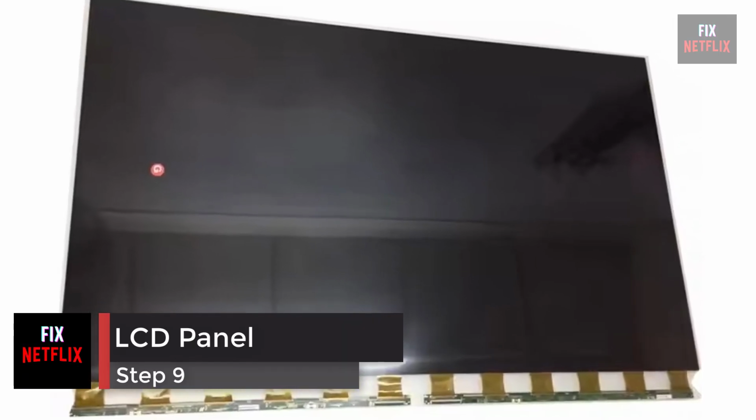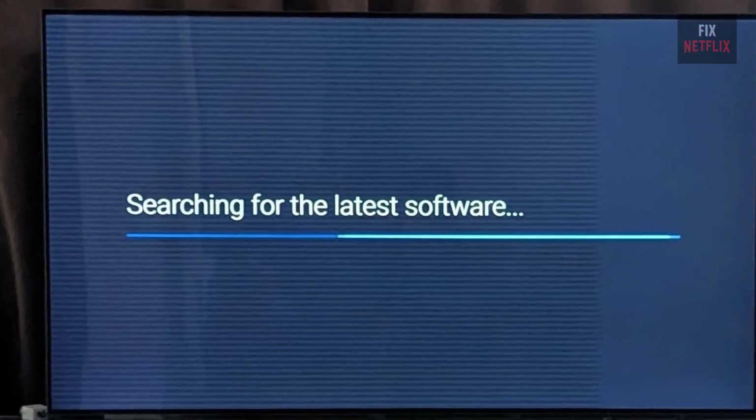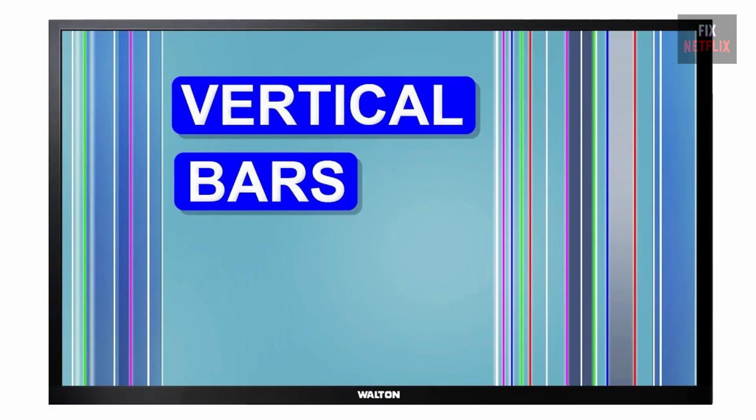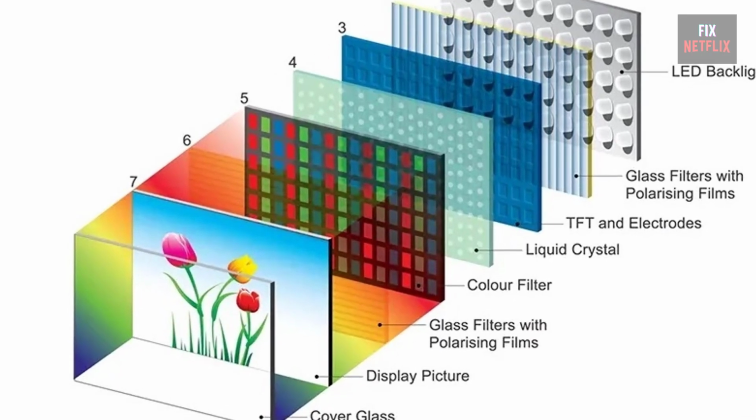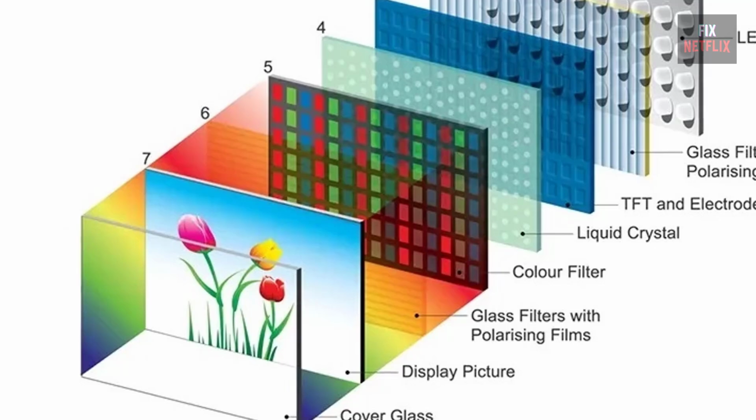Step 9. LCD panel. It is possible that your LCD panel has failed, especially if the bad backlight test showed no image. A common sign of panel failure is single horizontal or vertical lines in the image on the screen. Many panel failures can be traced to physical abuse. Further, the construction of the panels with chips embedded in flex plastic or attached to glass makes them vulnerable to unrepairable failures in those devices that surround the panel periphery.